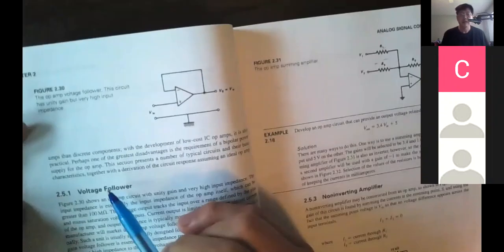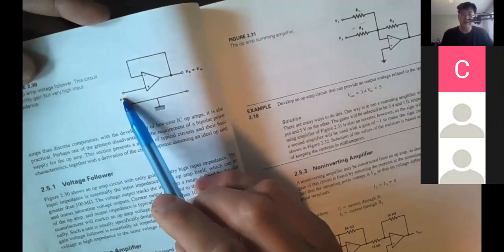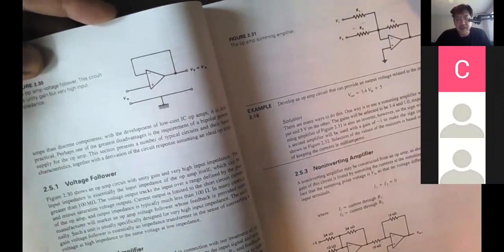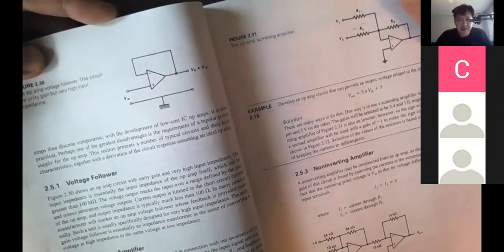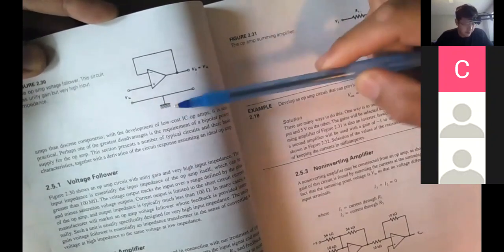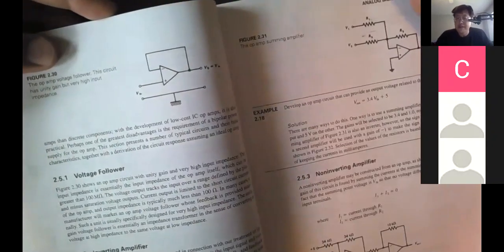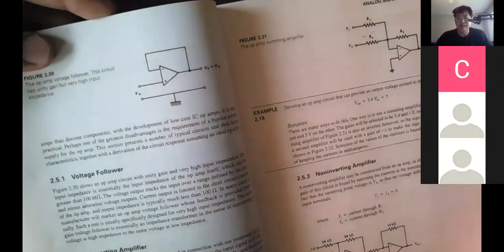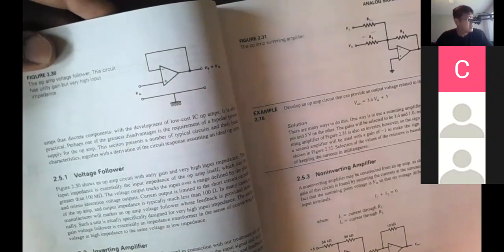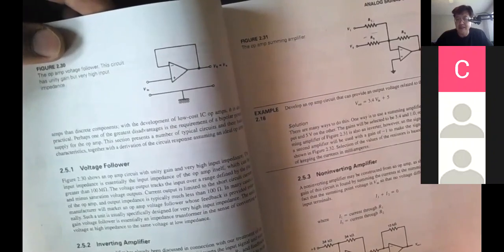So this is the amplifier where the gain is 1. That means the output equals the input. Whatever input you have here, the output will be identical. So it's a unit gain amplifier. Why do we want to do it? We didn't make it bigger, but we make it stronger. What do I mean it's not bigger? The voltage is the same, but the current is bigger. That means stronger.